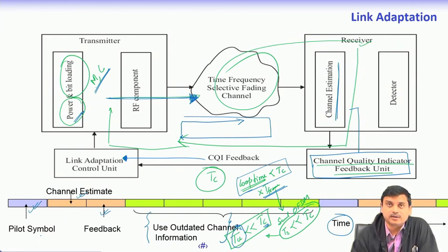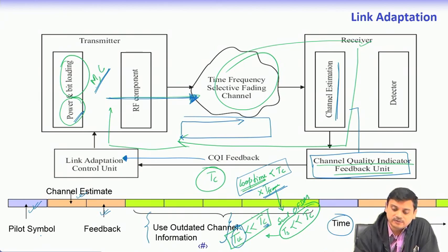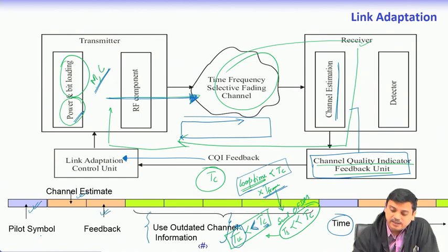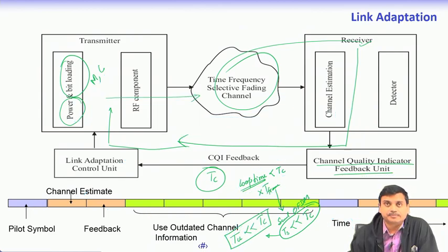This is very, very critical. So, effectively it means that our earlier condition that TU is less than TC is not sufficient. It should be much less than TC is the condition that we have to use. And we have also said that not simply TU, we should take TU plus TGI, which is the guard interval, into account and make it much less than the coherence time.